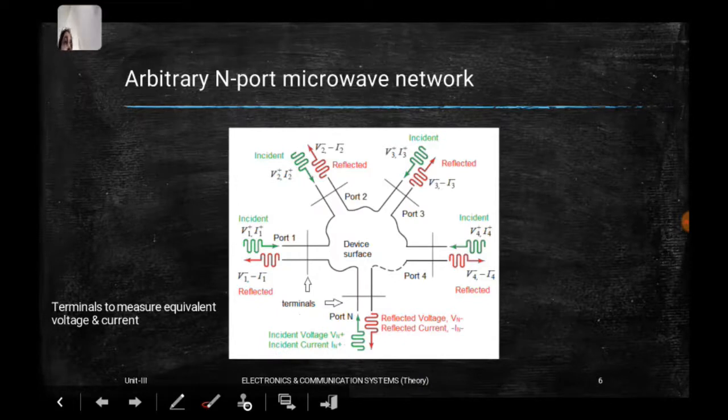Now, why we need the Z and Y parameters is to link all these voltages and currents together in one form. The form we use is because these are all linear superposition equations, and all are linked together. If you're able to write in terms of linear equations, I can write them in matrix form. I think you have studied the classical mathematical solution for linear algebraic equations by the matrix method. You can solve that and find the x, y, z values. Similarly, we can write the matrix form of this voltage and current relating to the parameters.